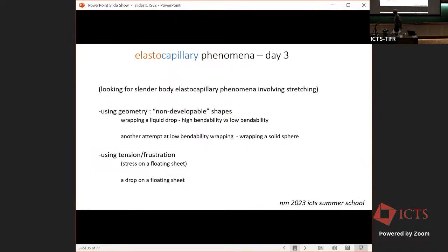Okay, so all the surface energies are comparable. The bending modulus is comparable. Sorry, the Young's modulus is comparable, but this guy is much thinner. Okay, so we went from a thickness of 10 micrometers and a bendability of about 10 to a thickness with these materials, we make them somewhere between 10 and 1,000 nanometers. So this is the thickness range.